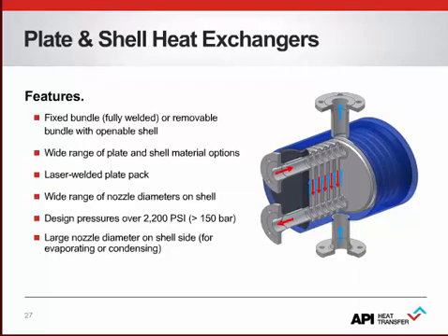The design is very flexible in terms of connection sizes on the shell side, as there is no limitation given by the plate holes. This gives the possibility to use these units also as condensers, evaporators, or even for complete gas applications on the shell side.